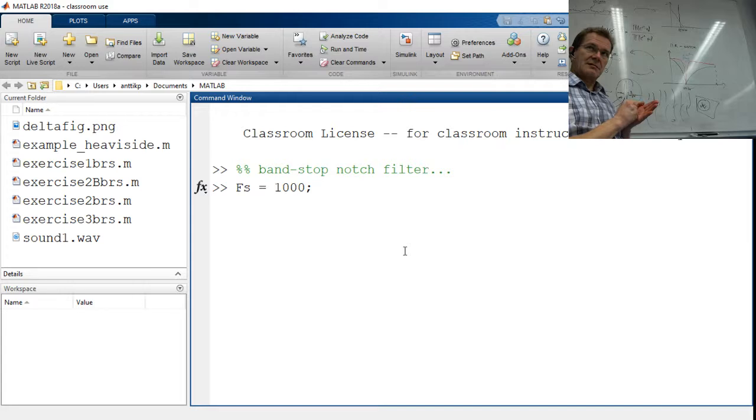Sallen-Key structure. The second-order Sallen-Key has one operational amplifier and two capacitors and two resistors, right? With gain, you have then 4 resistors. Is it like that?